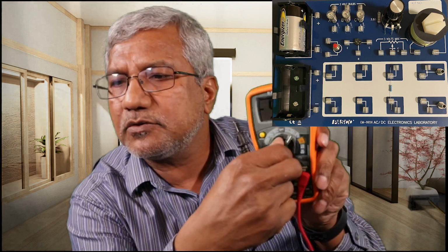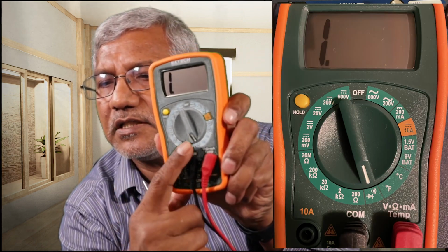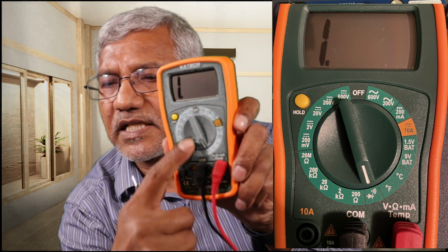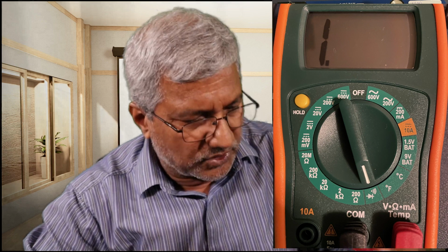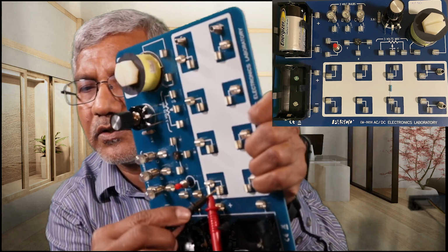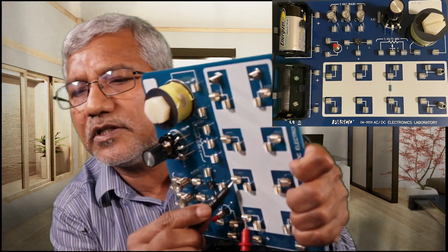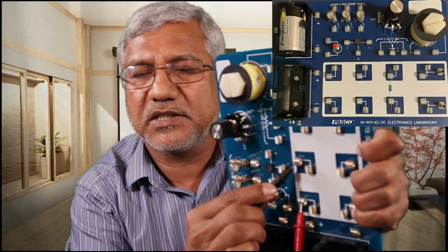And you got to turn on the multimeter, and take it to where it says continuity. I'm going to show you that. That's where it shows continuity. As you can see, put the selector switch there and then touch it. So after you put that, touch it here, and you hear that beeping sound showing there is continuity. But if you touch it on this, there's no beeping, which means there is no continuity. So that's how you use it.